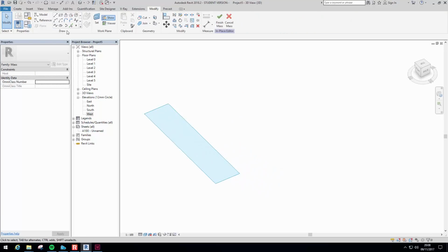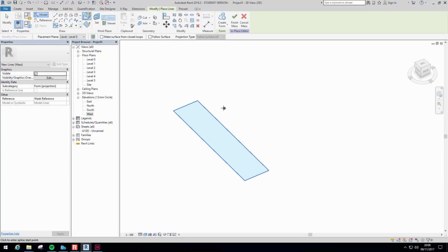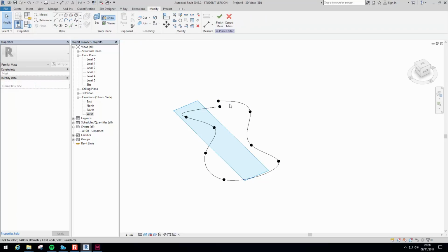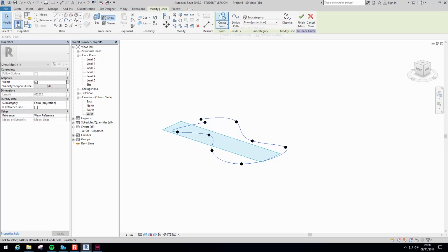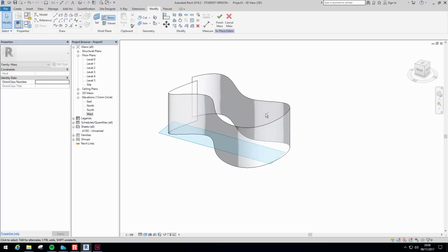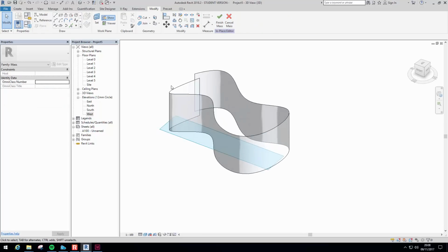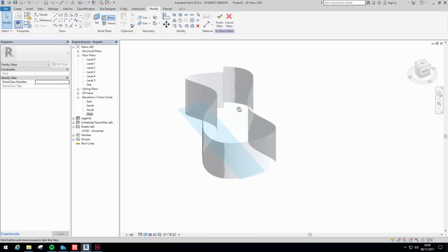So those are those tools. There's also what's called the spline tool, and the spline tool gives you curves which are a lot more fluid but are not what we say true curves. But you cannot add them together. You have to make it just a continuous line. If I select it, it won't create a solid shape, it will just create a plane along that route.